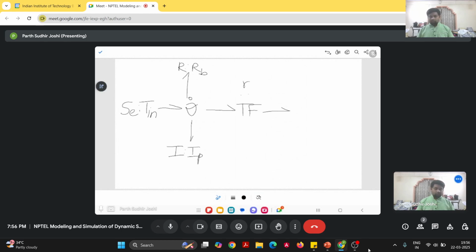For the rack, part of the energy is spent in moving the inertia, or the mass, of the rack, and some of the energy is being lost because of the friction or damping. So again we can write it as a one junction. There will be two elements: the resistance element, which will represent the viscous damping because of the friction between the rack and the guide, and another bond to represent the inertance or inertia of the rack.